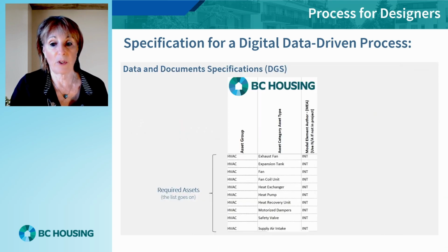The data and geometry specification is part of the BIM requirements and specifies the asset information requirements, the AIR in the ISO 19650 language. It specifies those assets that the owner requires from a lifecycle perspective and what data and design consultants need to associate to them.